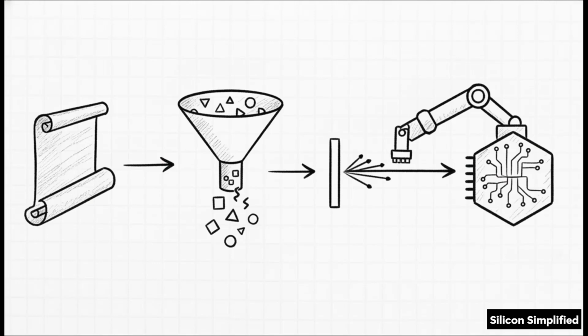Let's actually follow the lifecycle of a single data packet. It is born as a UVM sequence item, which is basically an abstract blueprint containing randomized data fields. A UVM sequence then generates a bunch of these items and fires them off to the UVM sequencer. The sequencer arbitrates these items and hands them off to the UVM driver, which finally gets to wiggle the physical pins on the hardware. It's a very clean, unidirectional flow of data.